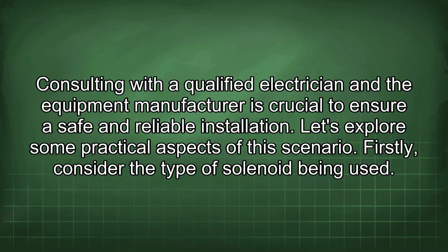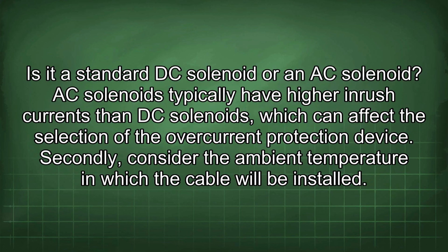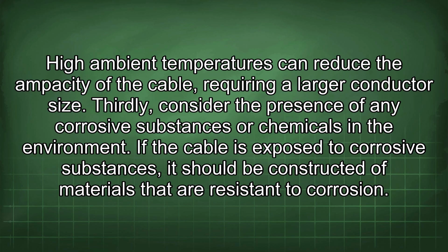Let's explore some practical aspects of this scenario. Firstly, consider the type of solenoid being used. Is it a standard DC solenoid or an AC solenoid? AC solenoids typically have higher inrush currents than DC solenoids, which can affect the selection of the overcurrent protection device. Secondly, consider the ambient temperature in which the cable will be installed. High ambient temperatures can reduce the ampacity of the cable, requiring a larger conductor size.